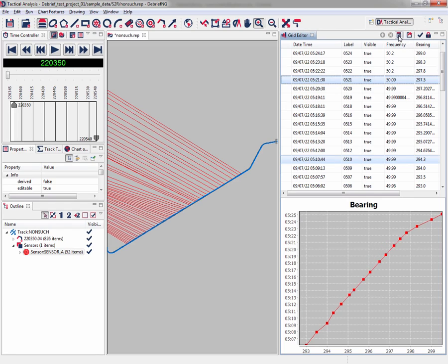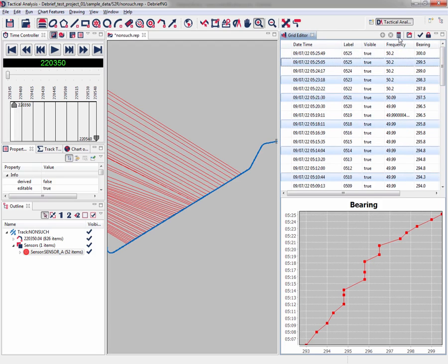It smooths the data out. But here we only selected a beginning point and an end point and then clicked on interpolate. And it did the interpolation based on those beginning and end values and those in between. However, if I undo this and I select multiple data points by holding down the control key and maybe even going beyond this, it's going to give us a better result because we're including more data points. So now we've tidied the sensor data, we can move on.